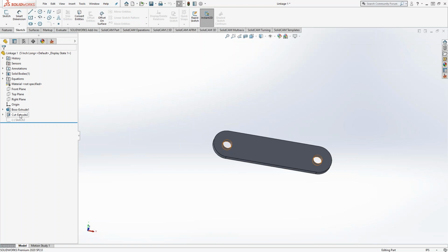And then when you go and do any kind of SolidCAM toolpath in either your mill turn or your milling, you have the ability to pull up a different version of that solid. It's really useful for when you're doing unique stock inside of milling. To eliminate air cuts, you can actually bring in that unique stock that represents the turned stock, and then set that up as your stock.